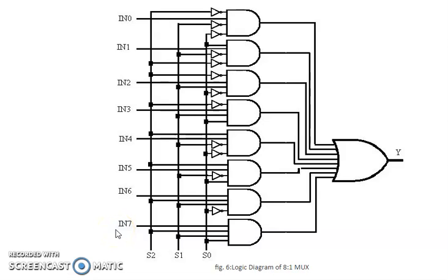There are 8 inputs, and these inputs are directly connected to the AND gates. The 3 select inputs decide which AND gate will be enabled at a time. Whichever AND gate is enabled flows across the OR gate. So the final output is whatever the content of the enabled AND gate is. For example, if the first AND gate has content 1 and the rest are all 0, our output will be 1.